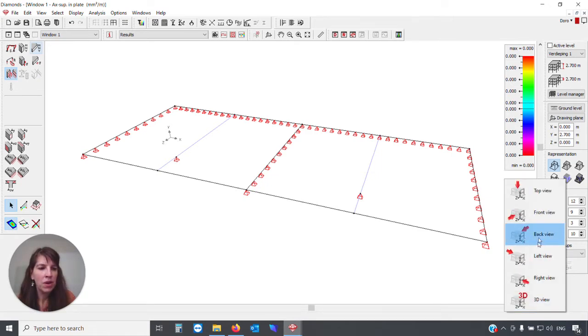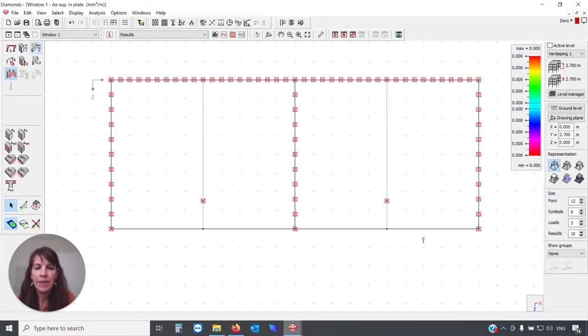Now I'm going to a top view, and as a general rule of thumb, you may average over a zone of about 2.5 times the dimension of the column, measured from the axis of the column. So that means that we can go 2.5 times to the left, to the right, to the top, and to the bottom. So the averaging width is about 5 times the column dimension.